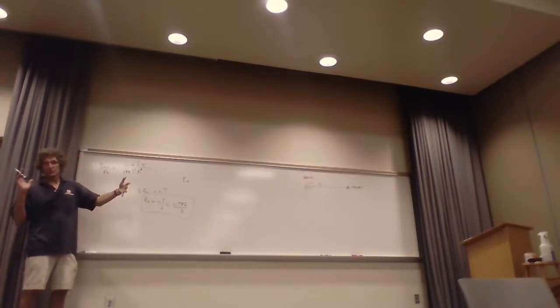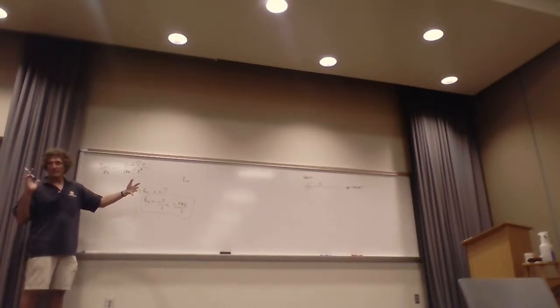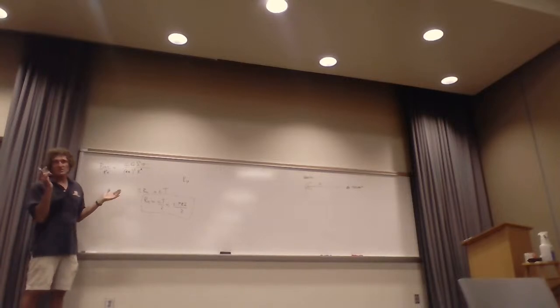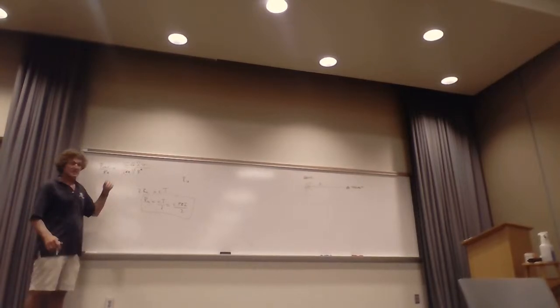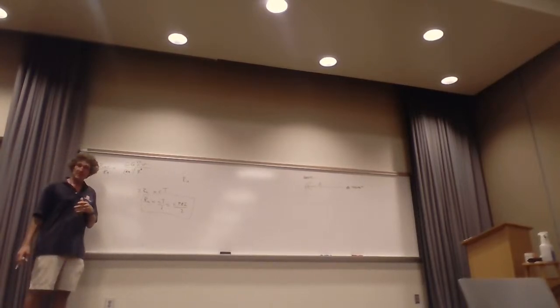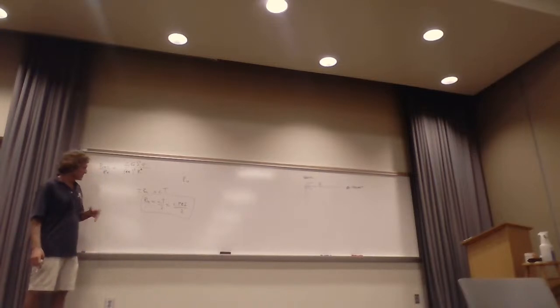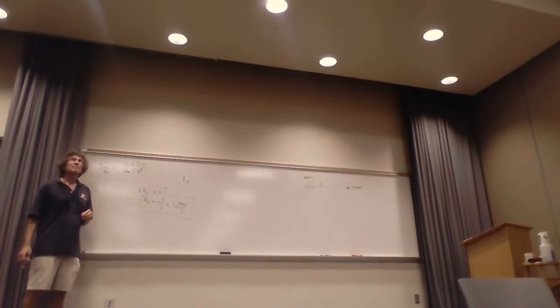Now I can gauge what my T is, my pulse repetition interval. This is one way of back engineering. In other words, all this stuff is linked based on the size of the object, the frequency, the gains of the antenna as well. But I'm trying to give you some perspective on it. There's a lot more to this. I'm just giving you the basic. So that's the maximum unambiguous range.